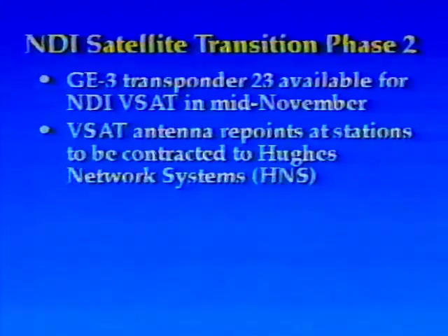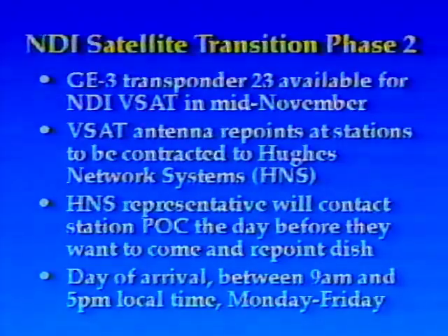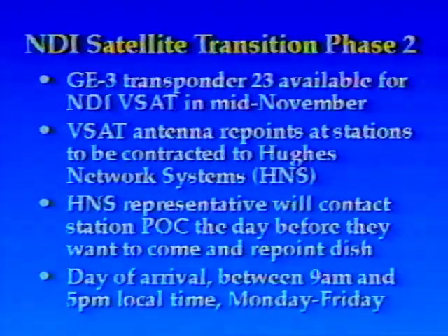A Hughes representative will contact the station point of contact the day before they want to come and repoint the dish. On their day of arrival, they'll get there sometime between 9 a.m. and 5 p.m. local time, Monday through Friday. They just need to get access to the dish to repoint it. They will then coordinate with the SoC to recommission the site on the new bird.